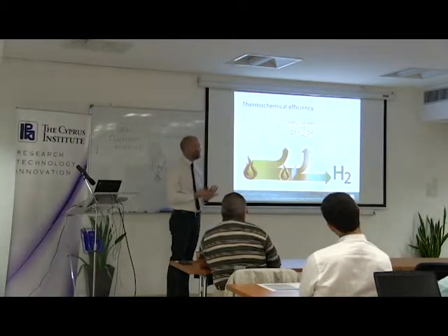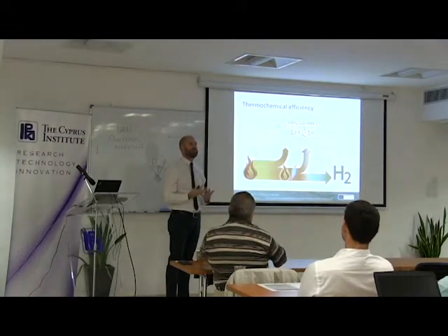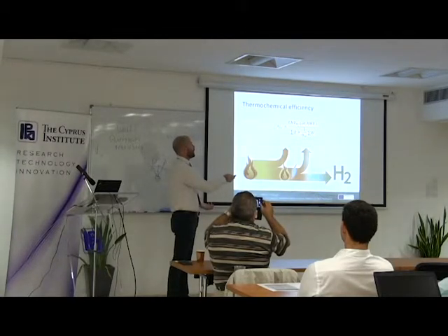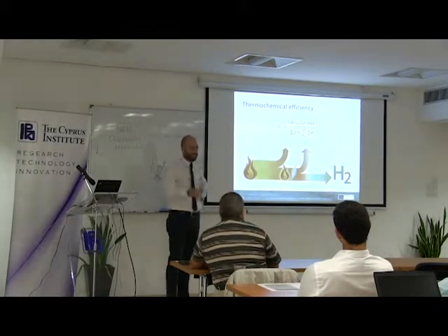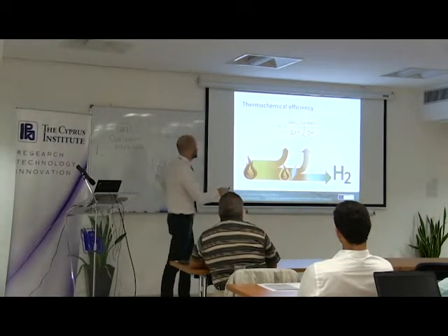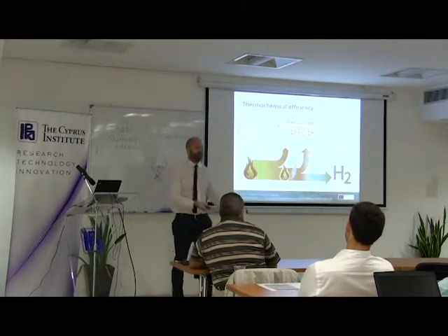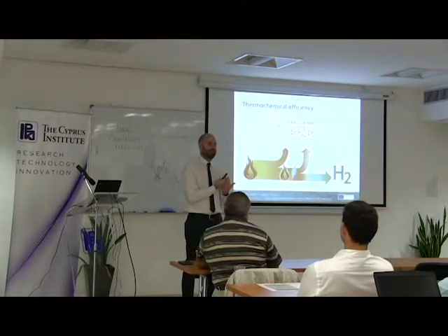Usually, very often, too often I would say, people just calculate the efficiency of these processes as the lower heating value or higher heating value. You can decide which you prefer, provided that you declare which type of heating value you are considering, of the hydrogen produced divided by the total energy input that you put in your process. Of course, this is not fair here.